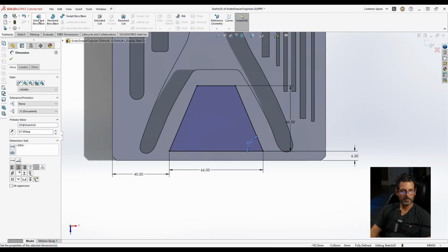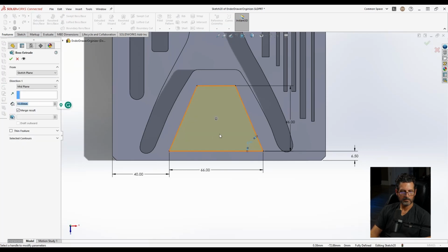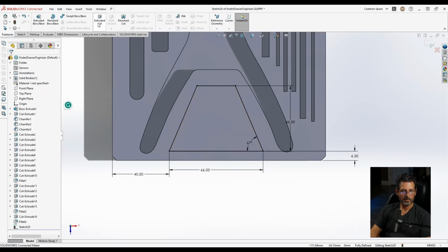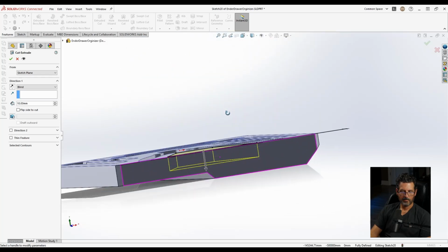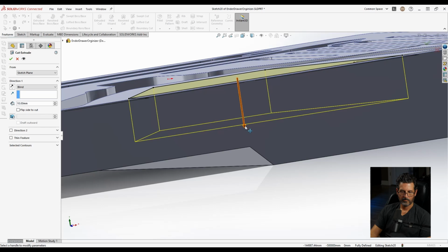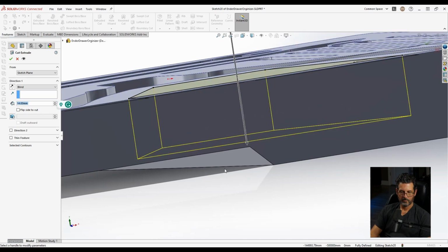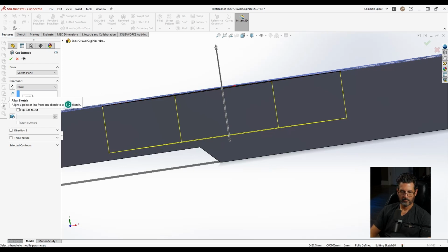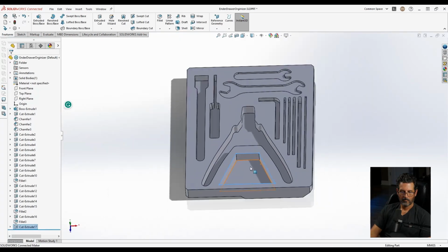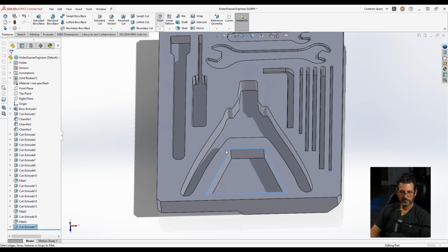Features. Extrude. No. That was extruded boss. I don't want that. I want extruded cut. And now we want to just make it where it doesn't break through. Make sure we don't. That's 15, so let's make it 13. Like that. And give it some fillets.